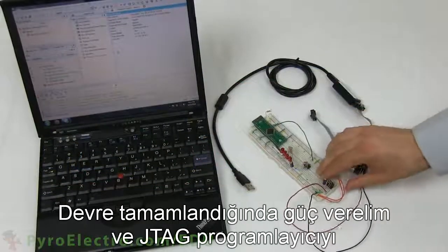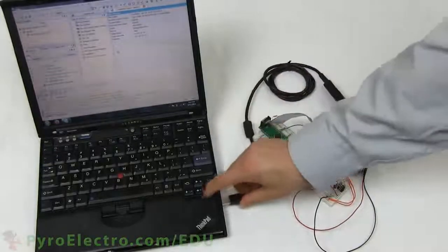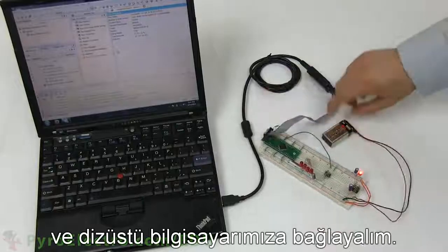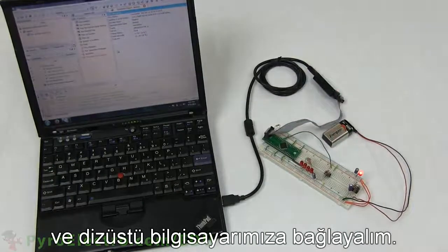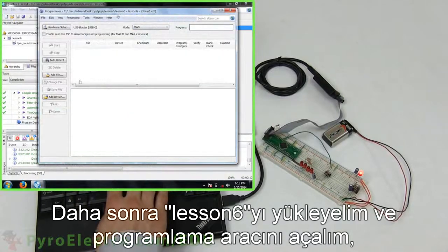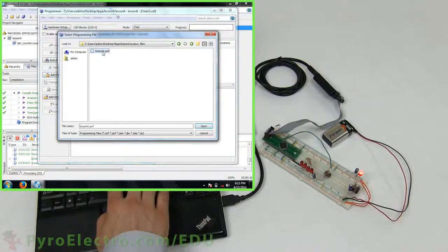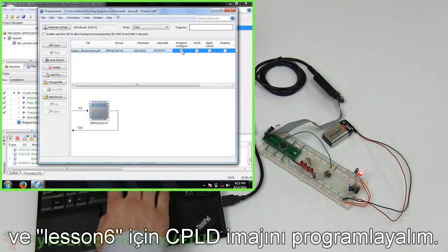With the circuit built up, let's power it up, connect the JTAG programmer to the CPLD board, and the other end to our laptop computer. Then we load up lesson 6, and let's pull up the programmer tool. Add the .pof programming file, and then program the CPLD image for lesson 6.